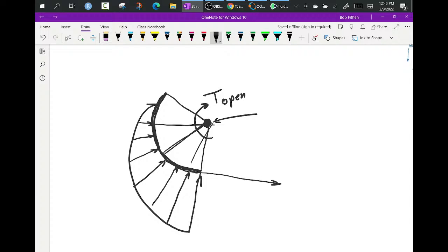So if the gate weighed nothing, the torque to open it would be 0, but the gate is going to probably weigh something, probably quite a bit. So all you've got to do is overcome that. I don't think this is what they do, but you could actually weld a big long rod there and put a weight over it, and then your center of gravity would move over.